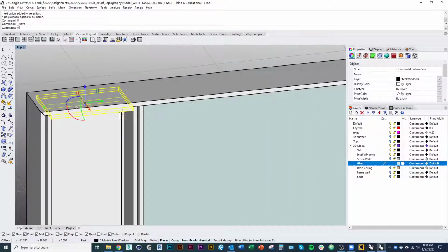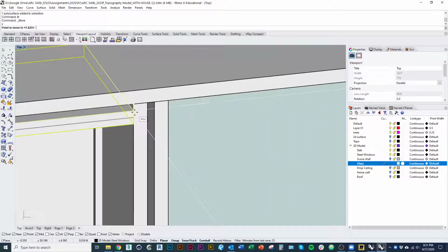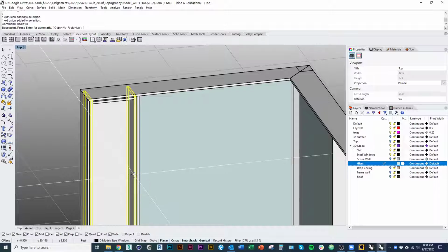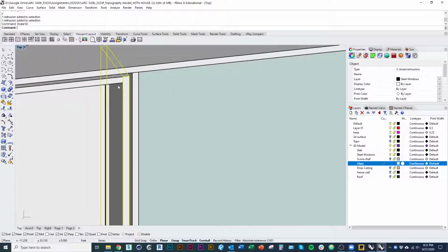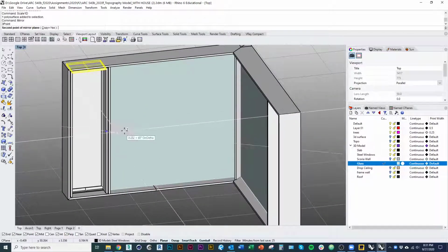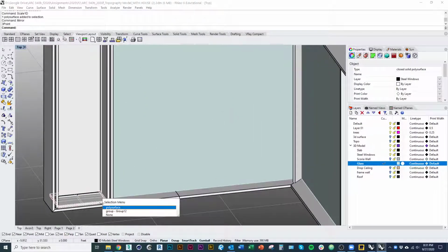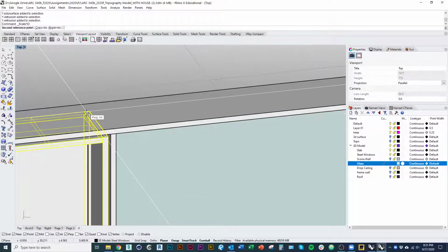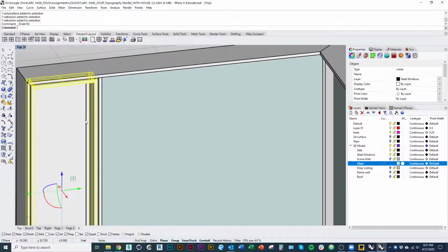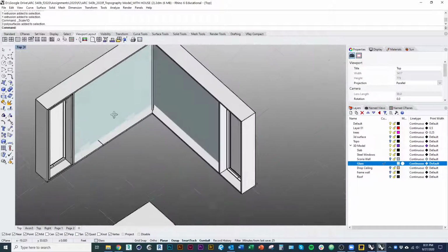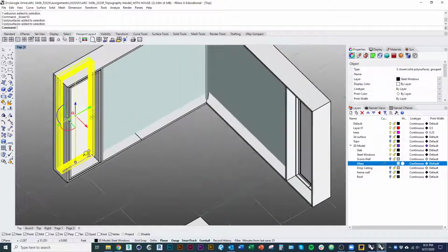Yeah, so I'm going to move this down by half. Move vertical. Midpoint. So I'm going to scale 1D these guys from the midpoint. Line them up. I'll mirror this guy. Go 3-point again across the midpoint. Make sure the option copies turned on. So, okay. Scale these back. And then we could draw the additional framing in there to show the operable window.